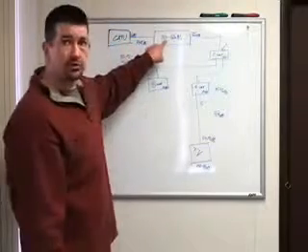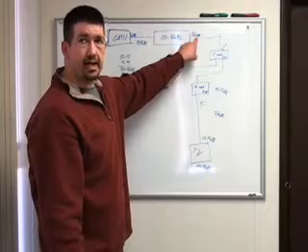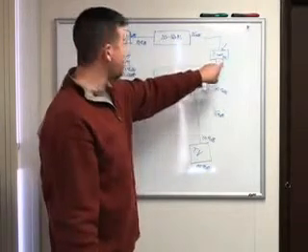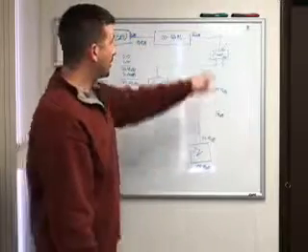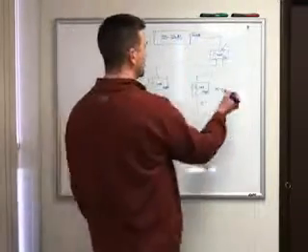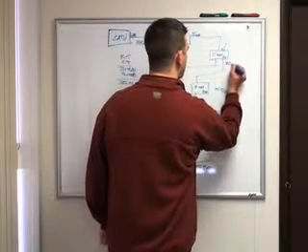So just to go through our completed system, we have 6 dB coming in from the cable company. That's hitting our amplifier, which has 20 dB of gain. So we have an output of 26 dB on the output of our amplifier going into the input of our two-way splitter here. So our two-way splitter is going to have 3.5 dB of loss, which is going to knock our 26 dB signal down to 22.5 dB.